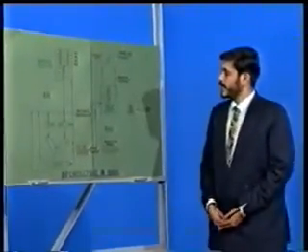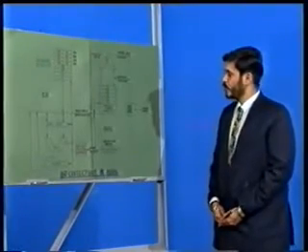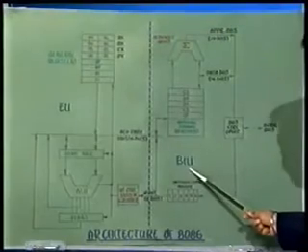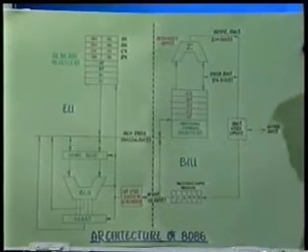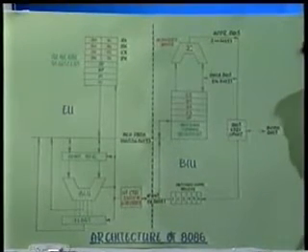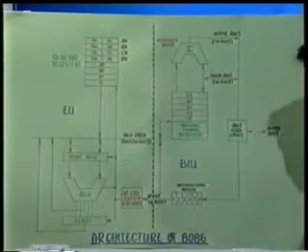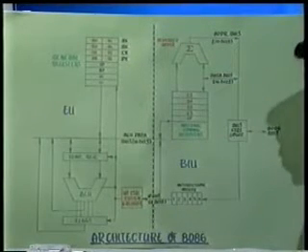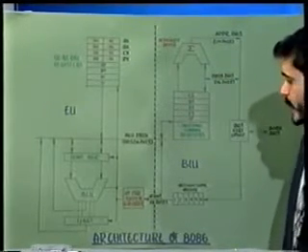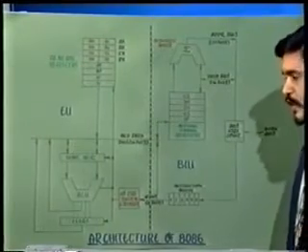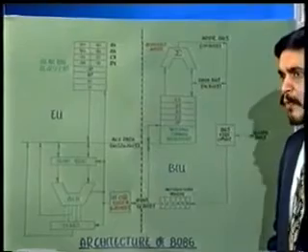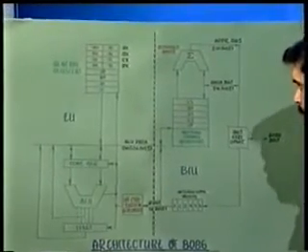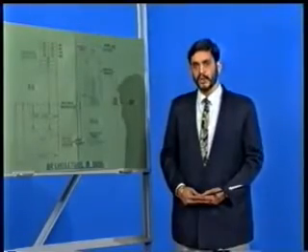As mentioned earlier, internally the 8086 is divided into two main parts, the bus interface unit and the execution unit. The bus interface unit provides all the external bus control functions, including instruction fetching and queuing. The execution unit decodes and executes the instructions. Both these parts work simultaneously, thereby providing parallel processing. Let us see the details of the execution unit first.